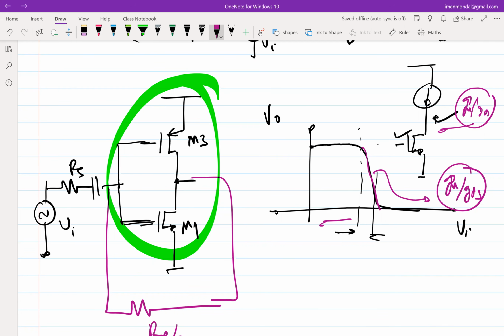But you cannot assume that, because now it's not a current source but a MOSFET, biased with a constant voltage. If you're neglecting the GDS of the MOSFET, then what happens? It will offer a resistance of GDS, but that is when it's in saturation.